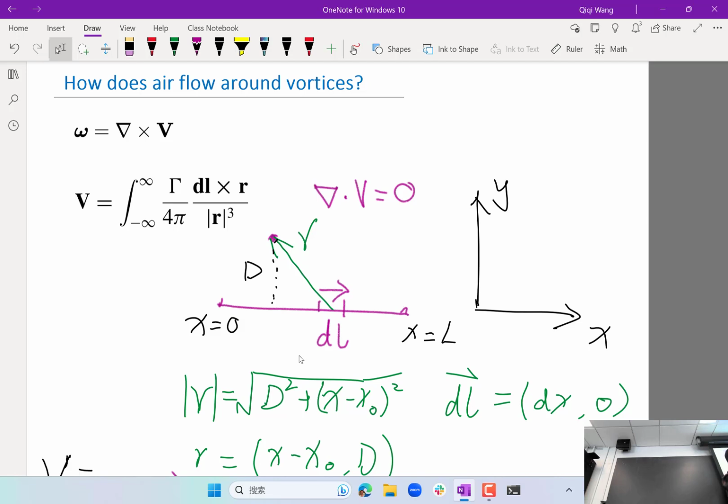So essentially, the amount of information contained in the vorticity field is only equivalent to 2 components. It's not like 3 independent components of information. So you need 1 additional scalar field to uniquely determine the vector field V, right? And that additional scalar field is actually the divergence of velocity.